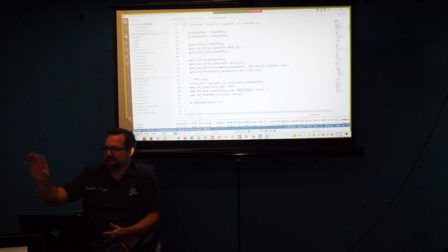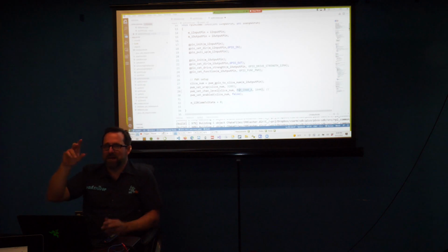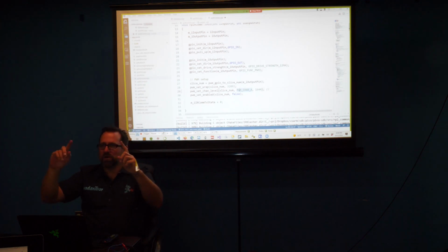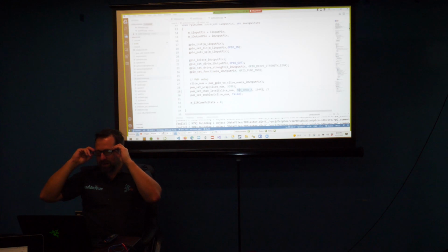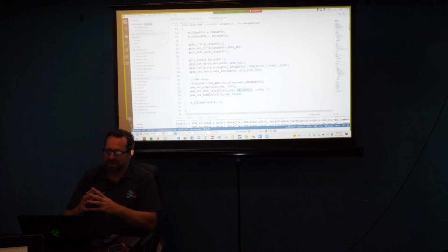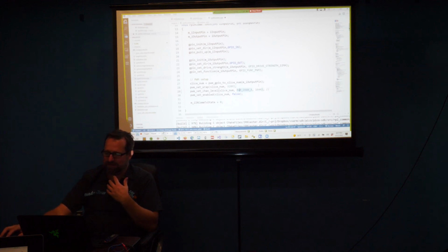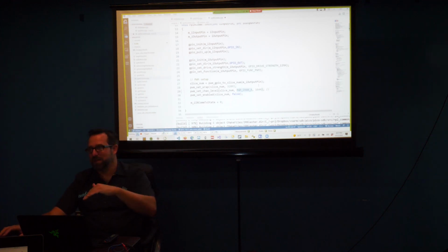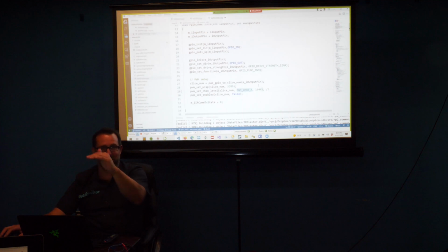Basically, you're absolutely right. There are only 8 PWM peripherals, but each one can control 2 outputs, and those 2 have to share a frequency, but they can have different duty cycles. Yes. But each GPIO belongs to either channel A or B of a PWM. So that's the trick: if you change the pin number you're generating the PWM on, you have to make sure you're on the right channel, A or B.